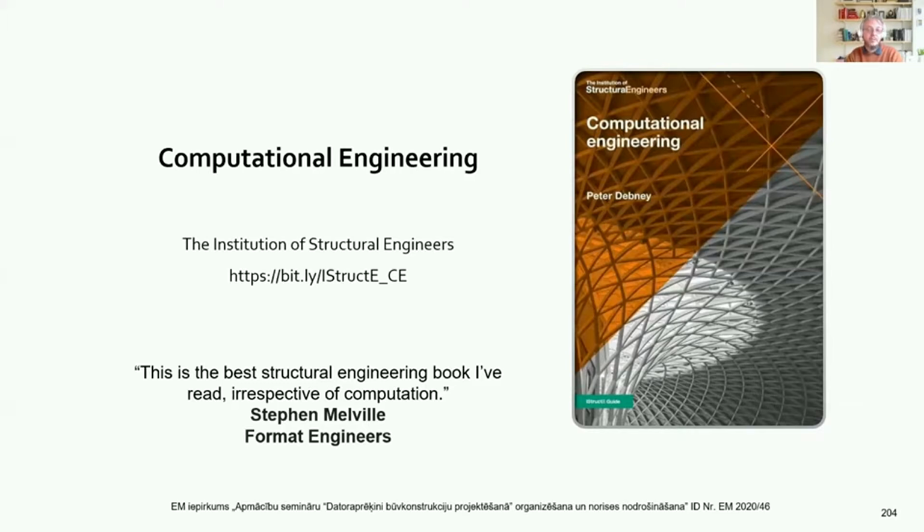If you're dealing with 2D or 3D, then the Poisson's ratio can have an effect. So yeah, I'm not sure when you would want to set it to 0. I think there are sometimes recommendations in the literature that when concrete is cracked, then Poisson's ratio can be taken as 0. So okay, probably because of that, there was this question. Yeah, that must be it. I've got far more experience with steel structures than precast concrete. So I'm not a precast concrete expert.